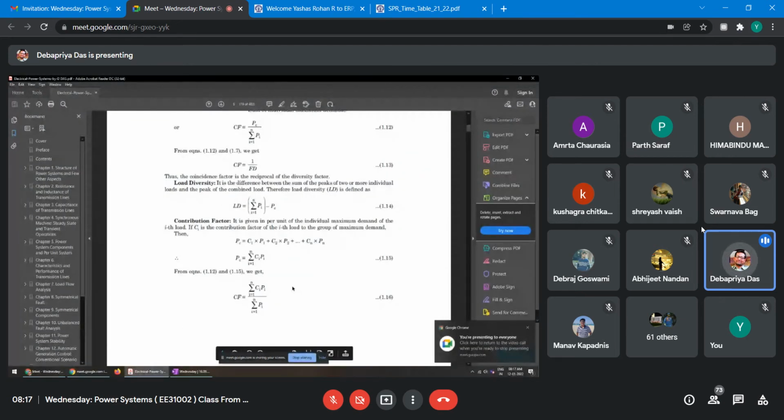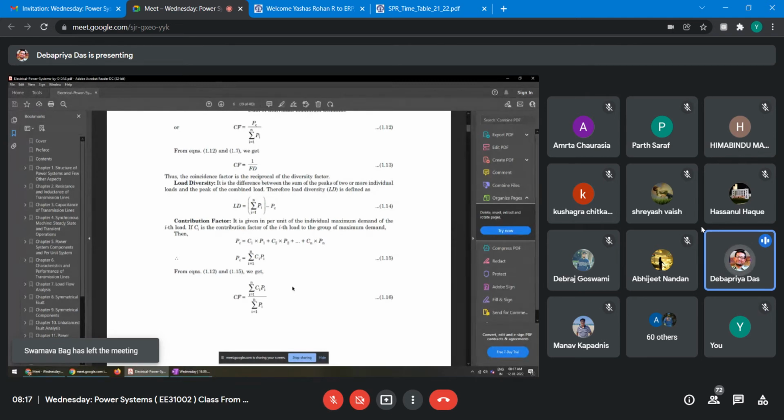So later I'll teach the per unit system. Before that, after inductance and capacitance, I have to teach these things, and after that the per unit system, because we represent everything as a dimensionless quantity. For example, in a transformer you have studied, say the low voltage side is 3 kV and the high voltage side is 11 kV. But in the per unit system, whether it is primary or secondary, you will find both the same irrespective of their voltage level. Later you will see that. Right, so that's why it is written in per unit, though not yet taught, but it will come later.